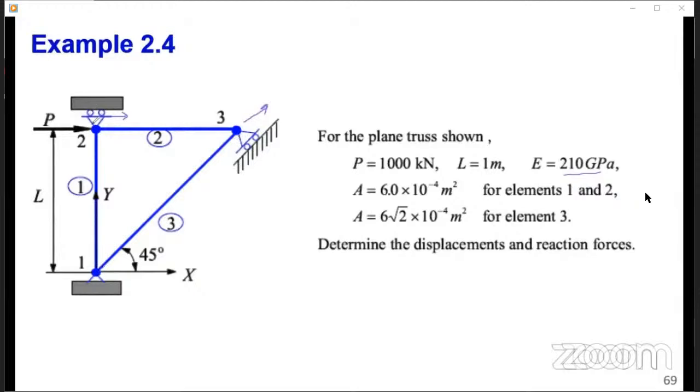Now, looking at support 2, being a roller support, you can have a vertical component and a horizontal component. So V at node 2 is equal to 0. These are things that you do by observation. V at node 2 is equal to 0. But U, because of the roller support, is a free displacement. Now, the interesting one is node 3. Node 3, we can only say with confidence that V3 prime, V in the local coordinate system, is equal to 0.